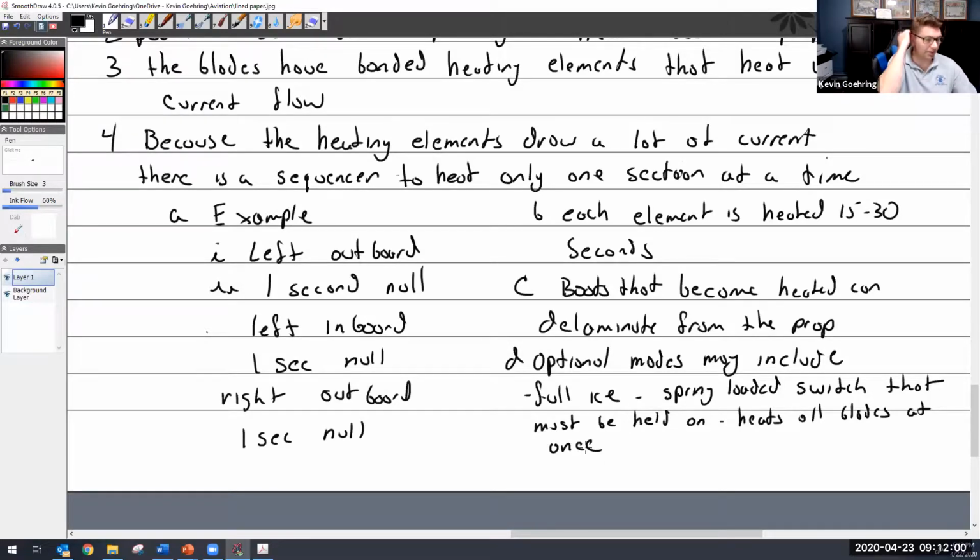So that was what I was telling you about, but you've got to hold it. So you can't turn it on and walk away. As a pilot, you physically have to take one hand off something, hold it in this full ice position and hold it there until maybe the vibration goes away. Thing about ice is you can usually hear it leaving because it's going to hit the fuselage when it flings off. So you have to hold it on there the whole time.